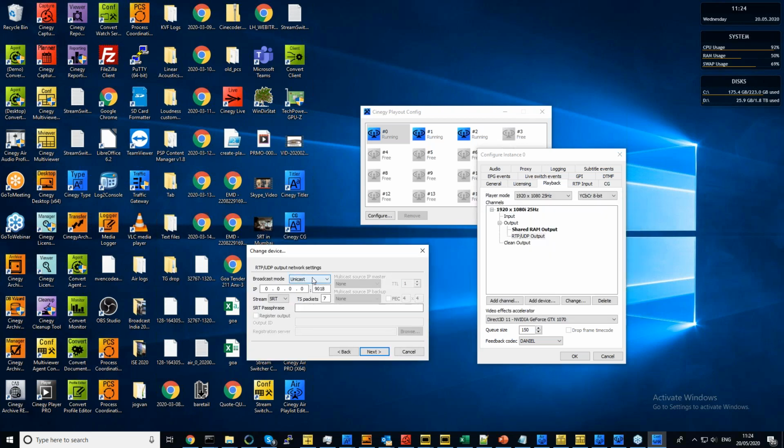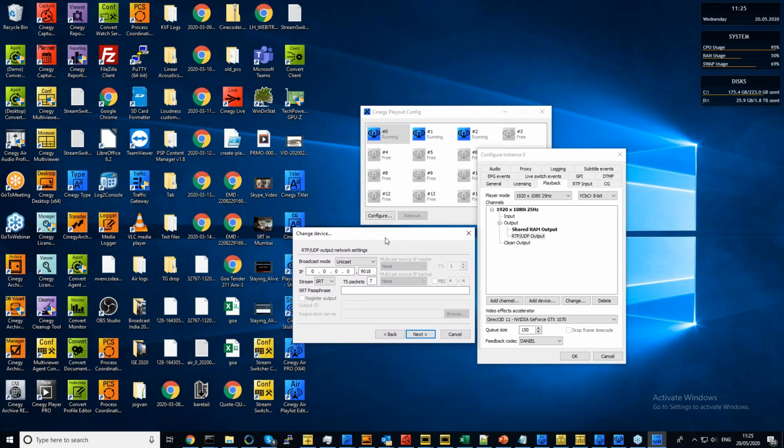Here we have the broadcast mode. If you set the broadcast mode to unicast, you'll be able to unlock SRT, set all of the IPs to 0 to be transmitting, give yourself a port. For our purposes for video signals, we're usually using 9,000 plus, but you can set it to whatever you want. Here we can put in an SRT passphrase that would be necessary at the other end to decode this using OpenSSL. Plenty tough enough to defeat even the most determined kiddies.